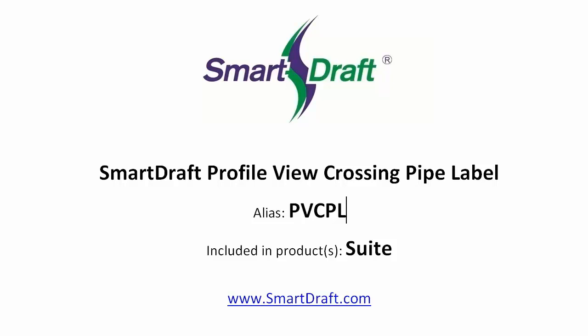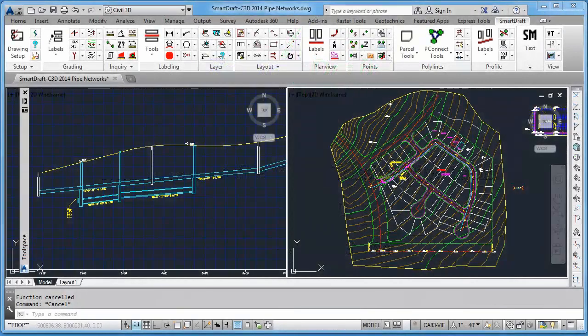This is a demonstration of the SmartDraft Profile View Crossing Pipe Label command. It can be found in the SmartDraft suite. The Profile View Crossing Pipe Label command is used to create crossing pipe labels for Civil 3D pipe network pipes shown in the profile view as crossing pipe.